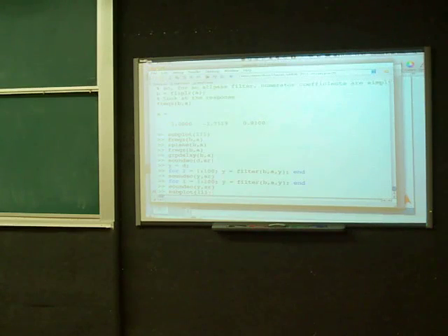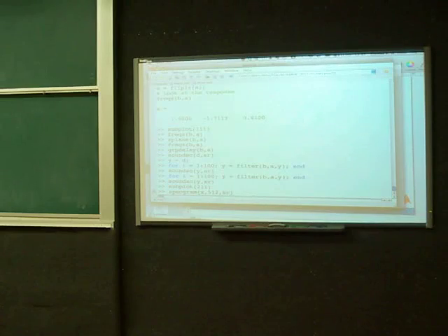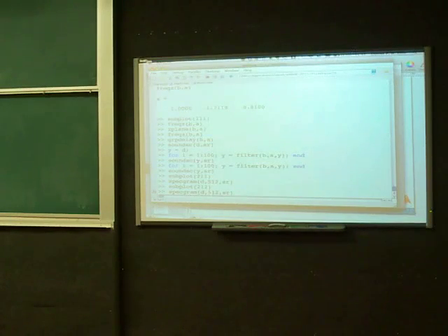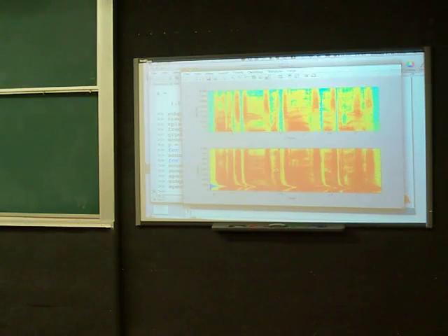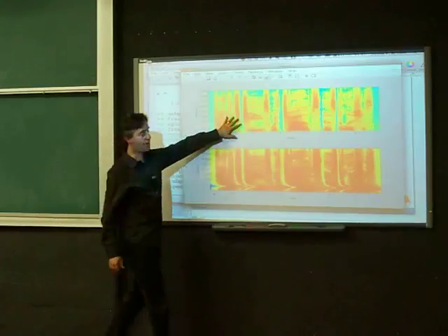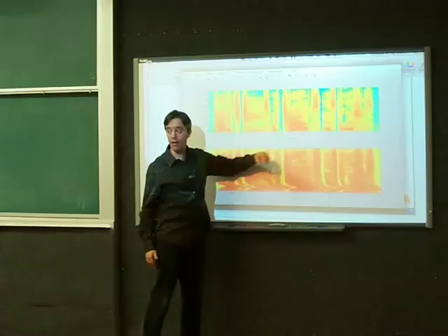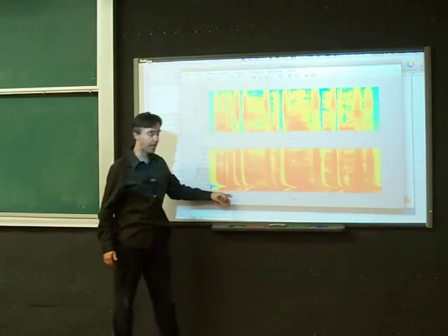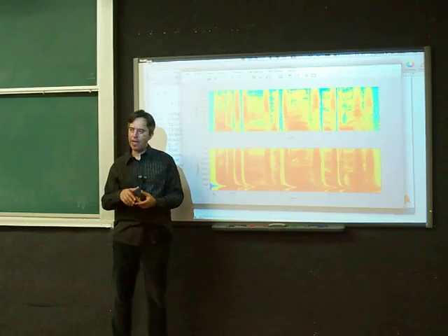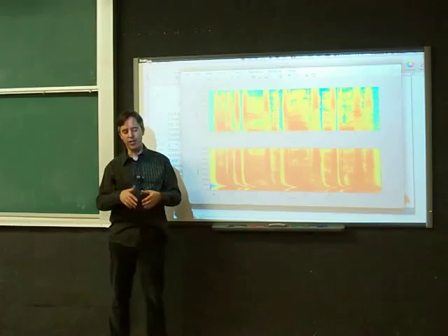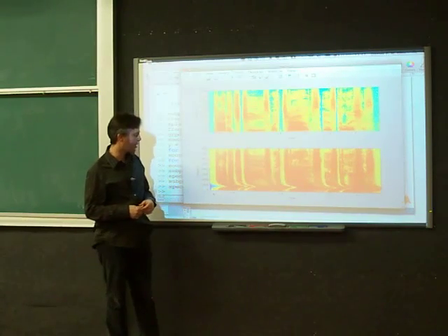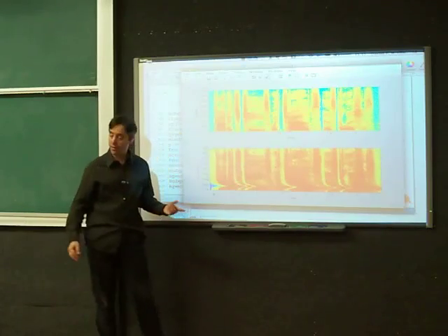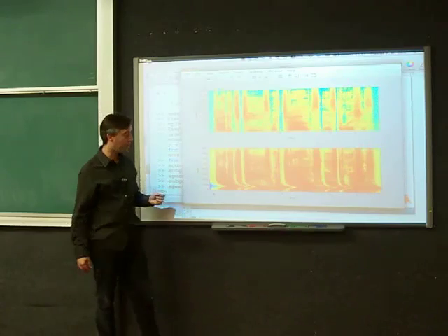And then if we look at the actual spectrogram here, you can see what's happened. So here's the spectrogram of the original signal. It's a speech signal, and we see these onsets at the beginnings of every syllable, every different speech sound. And then here's what happened after we put it through that filter 200 times, which meant that if it was delaying it by about 20 samples each time, then 200 is 4,000 samples, and is that right? Yeah, that's right. This is a 16 kilohertz signal, so 4,000 samples will be a quarter of a second.